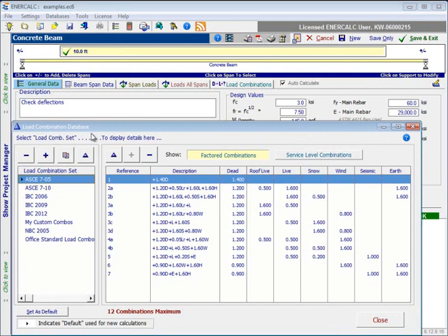This opens up the load combination database where we list the load combination sets that are on the current machine, and I would add that Structural Engineering Library ships with certain basic load combination sets as part of the system, but then from there you're able to use the add button to introduce new load combination sets that may be based on a particular code reference, they may be based on an office standard, they may be based on a particular client's or project's needs, and specified load combination factors that have been provided to you for a particular project.